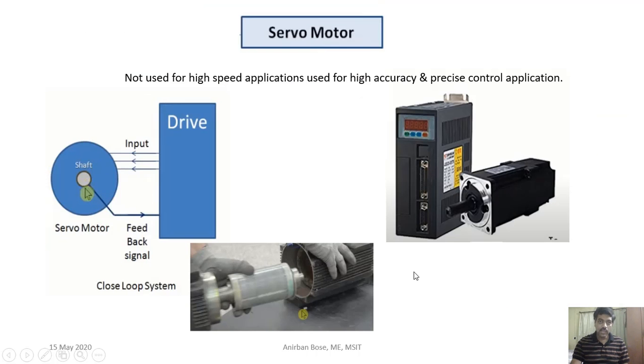Okay, now coming to the special motors, first we will see what servo motors are. Servo motor is a motor which works in a closed loop pattern. Already within that motor there is a closed loop control present, and these have different uses in robotics. It has use in industrial applications, CNC machines. These motors are widely used because of their high accuracy and closed loop control.